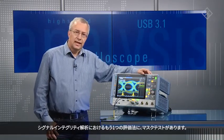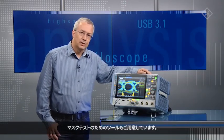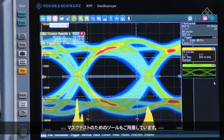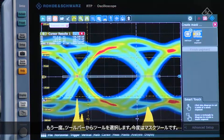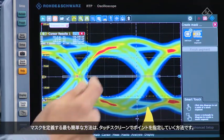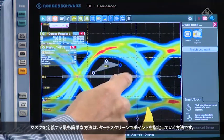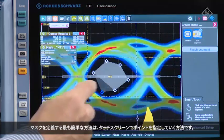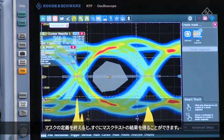An additional aspect for signal integrity analysis is mask testing. For that, we also have a tool. Again, I'm going to select the mask tool from the toolbar, and the easiest way of defining a mask is simply by defining the points with the touch screen. And finish the mask definition.